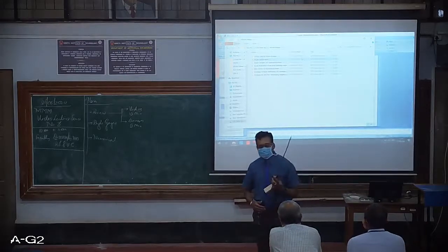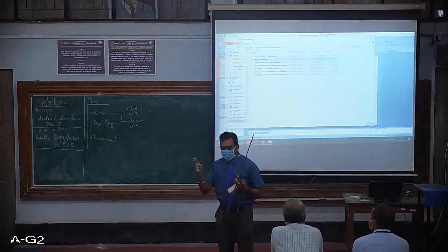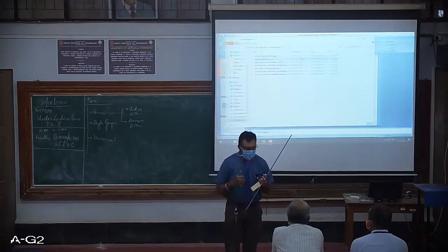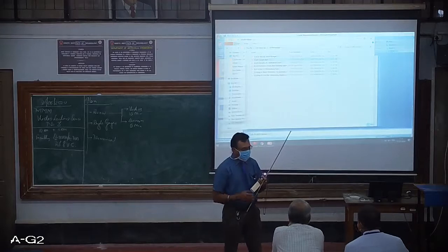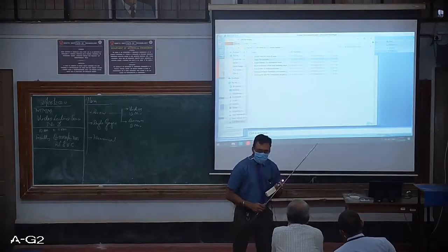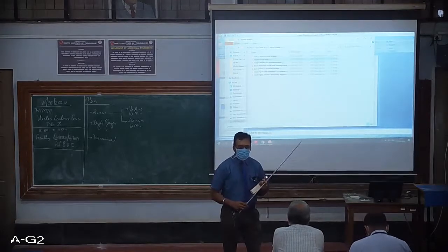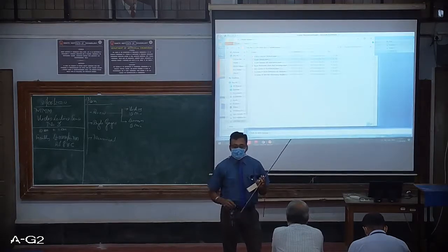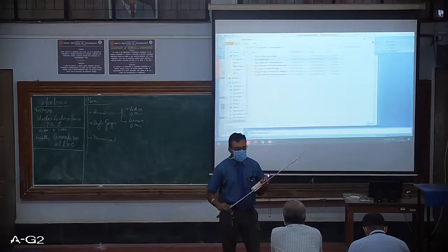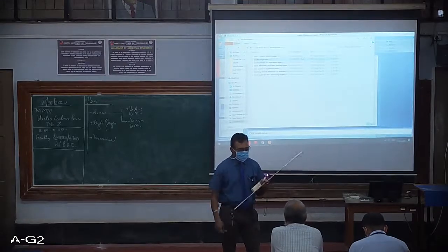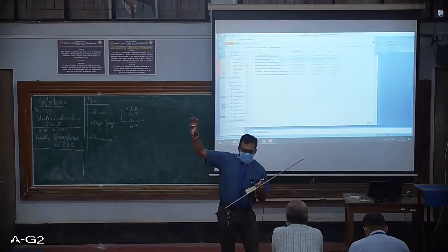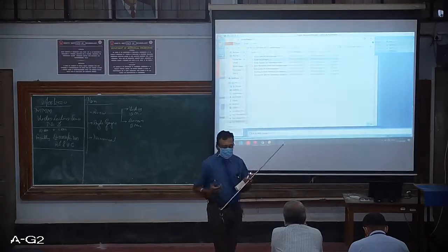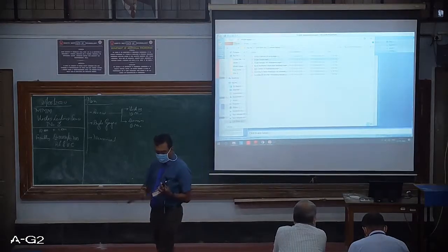The normal machining grades that we have are IT7, IT8. A good quality CNC lathe can give us IT7 or IT8. Drilling would give us around IT9, IT10. This is the range, and the roughest range, or the maximum tolerance that we can grade, is IT16, with respect to casting.